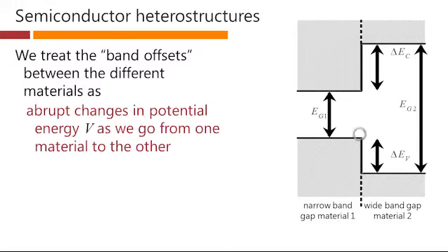And we get a similar behavior in the valence band, and in this case we should look at this upside down. This is a lower energy in this material for the holes in the valence band compared to the energy for the holes here, so we can consider holes with effective masses as well inside these layers, seeing lower energy in this layer compared to that one.